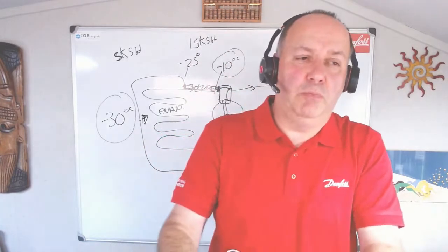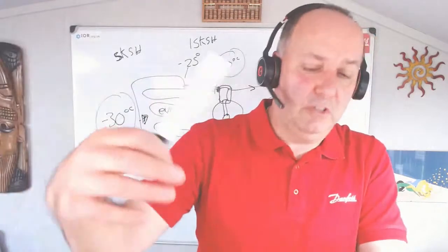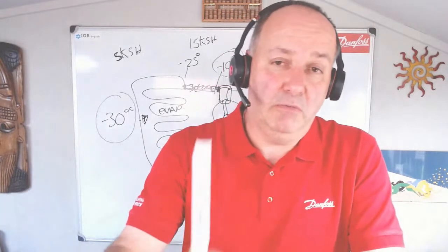the cold room operation and the maintenance is incredibly important. I've been to quite a few sites where I'll go in and the customer will be saying that we've got a problem with this Danfoss equipment. The first thing I'll do is go up and look at the evaporator and it'll be covered in ice. Or the fans might not be working, or the defrost heaters might not be functioning, or there are many reasons. But maintenance is, for me, a really good thing, and it needs to be done.